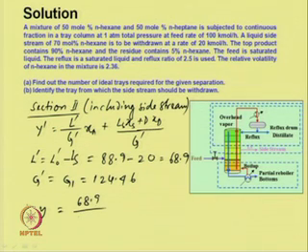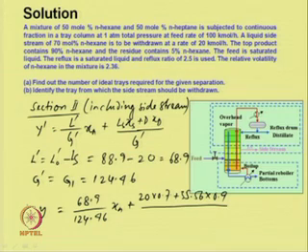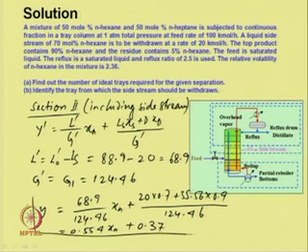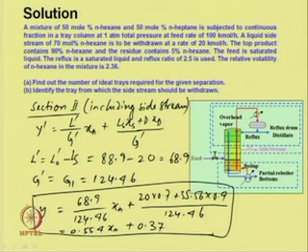So the operating line equation would be y is equal to 68.9 divided by 124.46 x n plus 20 into 0.7 plus 35.56 into 0.9 divided by 124.46. Which would be equal to 0.554 x n plus 0.37. So, this is the equation of the operating line for the intermediate section.